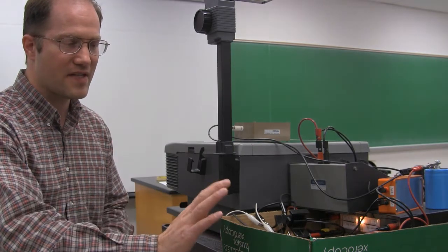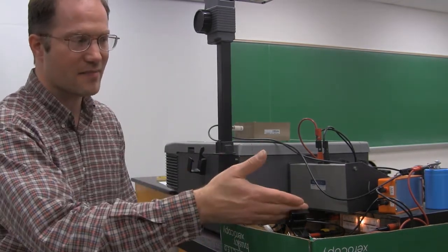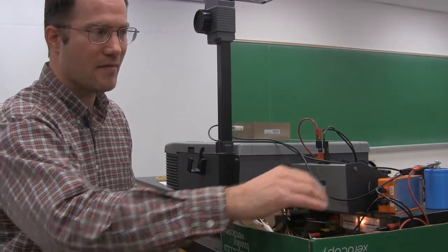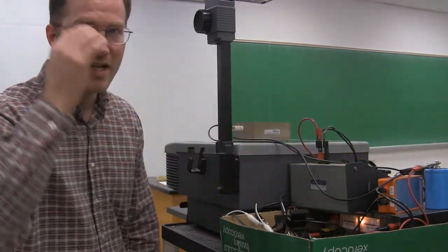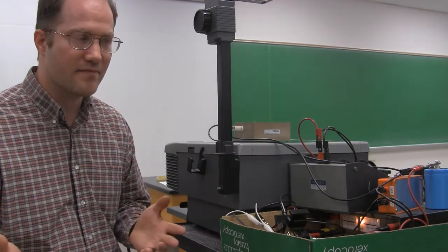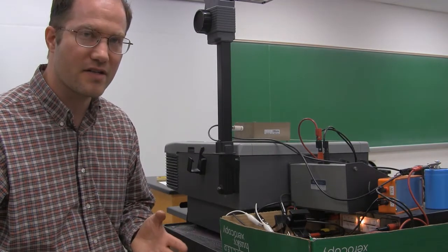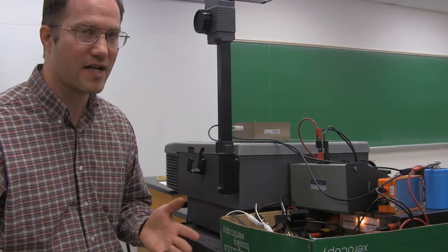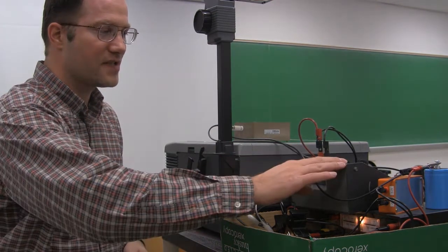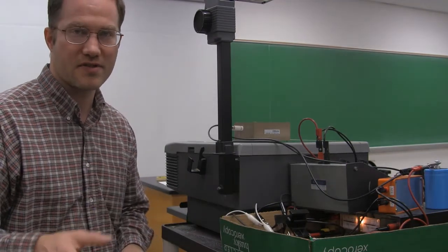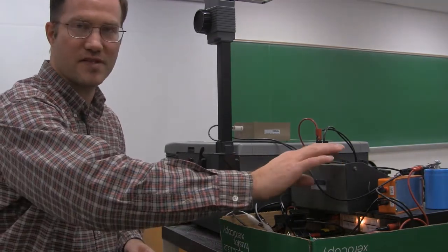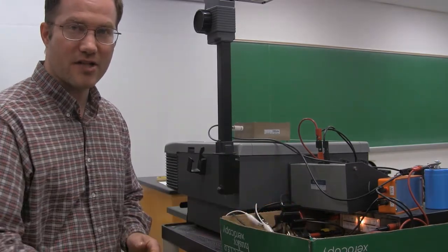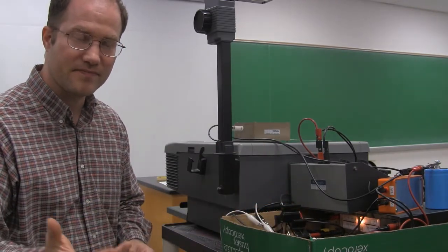And that is, we have this set up here. I've got a power supply, a resistor box. My capacitor is this blue thing here. The capacitors are rated at around 22,000 microfarads. How accurate is that? We'll see. 22,000 microfarads. Our resistor is going to be 1,000 ohms, just like the resistor at your table. There's a resistor in here that we're using. And then I have my switch, so I can charge the capacitor or discharge it.